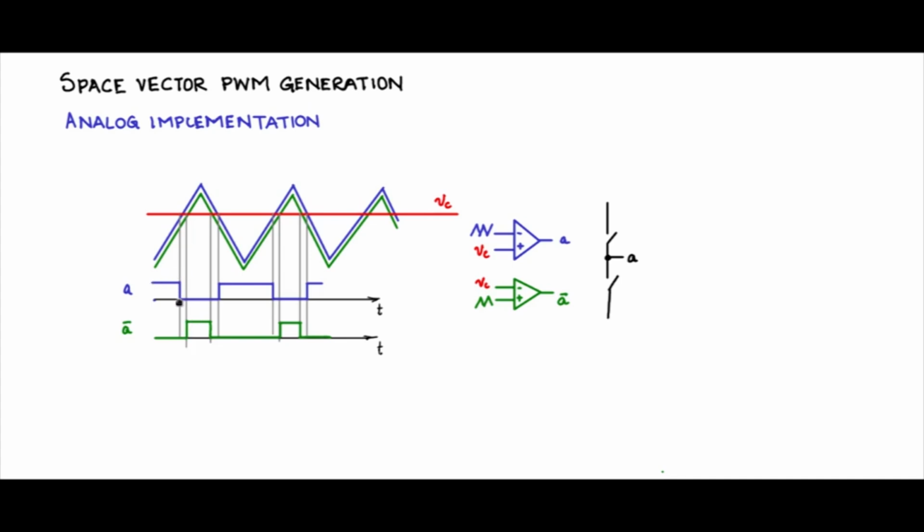Now you see the beautiful aspect of this is that during the transition, this is not a direct 180-degree inversion. As I was saying before, you have to give a dead time. When this is transiting down from on to off, and this is transiting from off to on, there is a period called the dead time. Likewise, when this is transiting from high to low and this is from low to high, there is a period where both are off. This is called the dead time, so that the top and bottom switches are given enough time for changing state, because they have finite rise and fall times. They are practical switches.